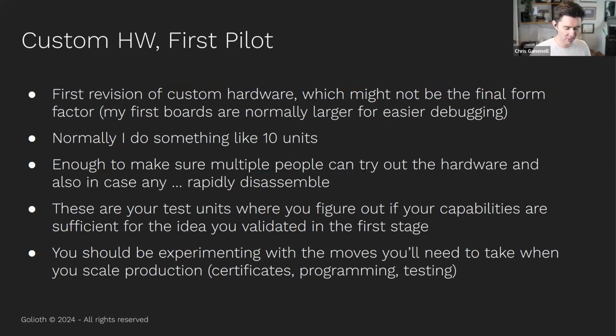And the main thing is you should be pulling stuff forward in your process as much as possible. I should have mentioned this earlier on, but when I said you don't know what you don't know, one of the things that'll be most useful in taking things to production is pulling the hard stuff forward. So things like testing and provisioning and programming, all the things that you're going to do in any kind of design, you want to be able to pull that forward as far as possible so that when you have problems with it, you can design it into your next rev of hardware.